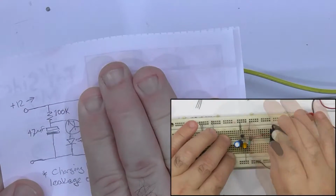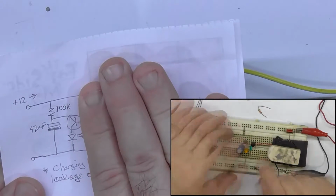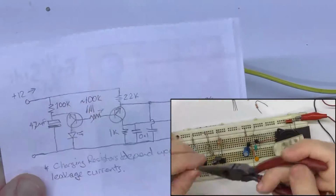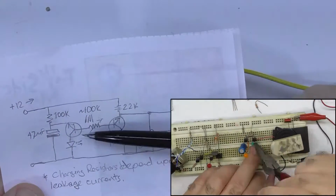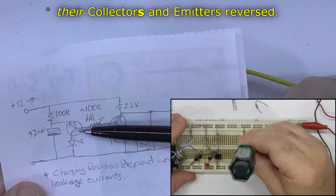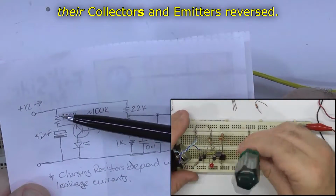You don't need, for oscillation, you don't need to have anything connected to the base. But what you do need is the transistor to have its collector and emitter reversed and an appropriate supply voltage.